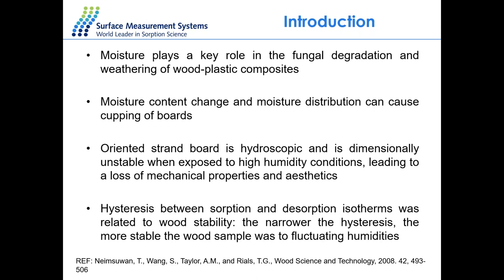One of the other parameters that we're going to have a look at is hysteresis, which is the gap between the absorption and desorption. When we pour water or vapor on top of a sample, it will uptake with a certain type of profile, and when we try to dry the sample, the profile will be different. The gap between the absorption and desorption profile, the hysteresis, represents how much water stays trapped and how much energy is required to remove that water. Some materials have a wider gap of hysteresis, some materials have a smaller gap, and that can cause a fluctuation in the water content of the material at each temperature and the total stability of the material itself.